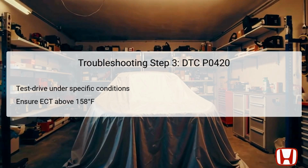It's crucial to maintain these speeds because it helps to simulate normal driving conditions while allowing the exhaust and catalytic converter to function optimally. Additionally, you will want to decelerate while fully closing the throttle to observe the vehicle's reaction. Performing this test drive 3 times or more ensures that any intermittent issues are identified and sufficient data is collected for further analysis.